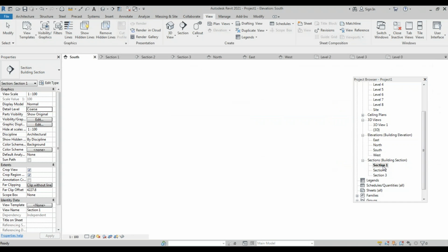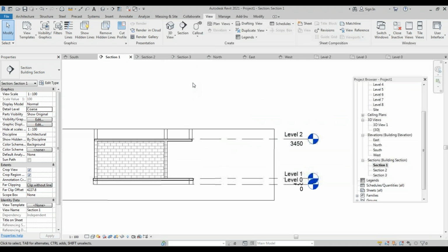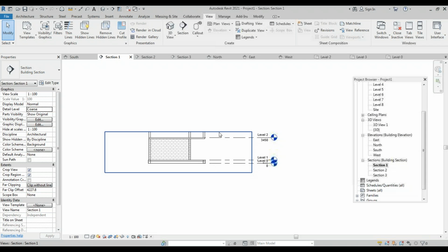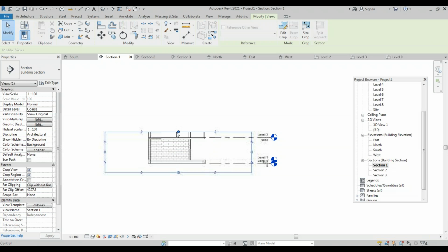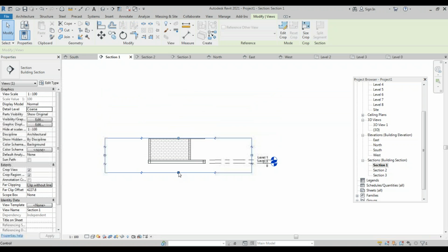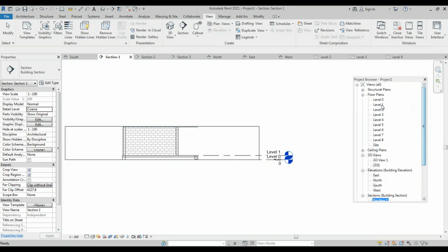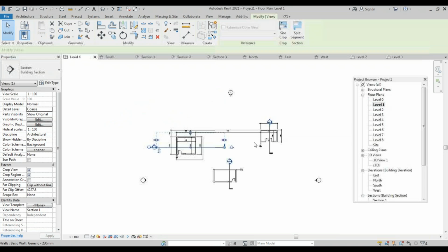It works very quickly. Your section is only from this level to that level. It doesn't show further, so nothing to worry. If you want the section to be seen, click on the section and drag it further up. So you'll get the section floor by floor. Yes, you can show like this. This is floor by floor. So this is how Revit works. It's very easy to get all these things generated very quickly. Okay. So, do you all follow what I say? Did you understand?